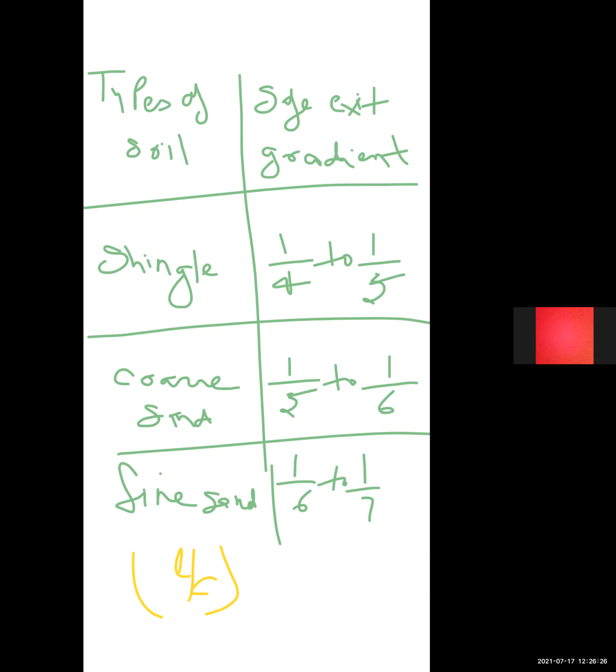So these uplift pressures must be investigated for various flow conditions, and the maximum uplift due to the dynamic action, that is the surface flow, should then be compared with the maximum uplift under steady seepage, that is for subsurface flow, and the maximum of those chosen for designing the apron and the floor of the weir.